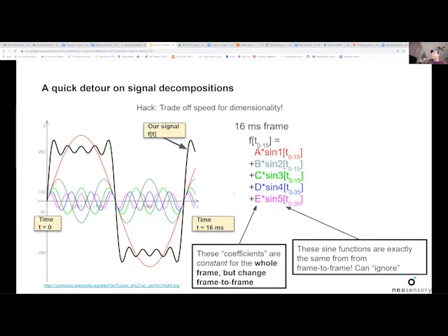period. So now what you've effectively done is you now have this one-dimensional signal which is changing very quickly over 16 milliseconds, and you've converted it to, in this case, a 5-dimensional signal. You have 5 values that have a constant value for this entire 16 millisecond increment.